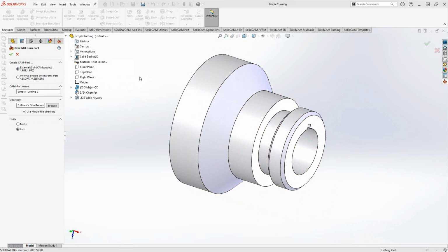And SolidCAM External is actually a type of assembly file. So it now has the ability to add in the vices, the clamps, the soft jaws, the tailstock, unique stock, anything you're looking to add to the model to better simulate it, to better program it. It being a separate file, and you have a copy of the model, you can make changes to it in terms of the design. So if you don't like this sharp edge and you'd like to make a fillet or a chamfer on there, you can actually go in there, make that design change, and that design change is not seen by the original design model.